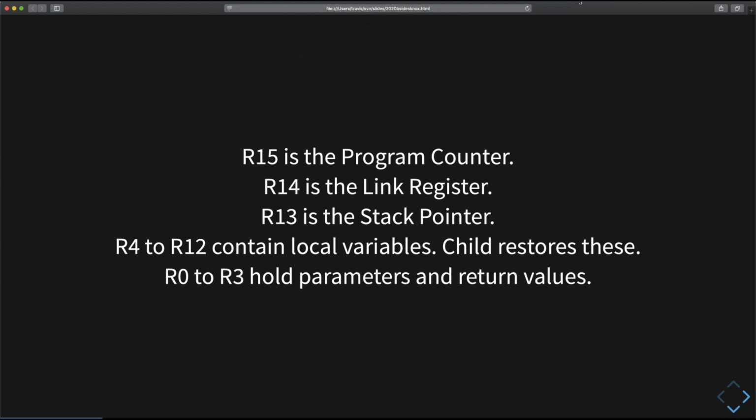The registers are different than an x86 or AMD64 in that someone put some thought into what they should be and decided to give them meaningful names instead of conglomerates of all the backward compatibility history of the platform of the 1970s. R15 is what you think of as the instruction pointer in an x86. We call it a program counter or a PC in RISC chips, but it's the same thing.